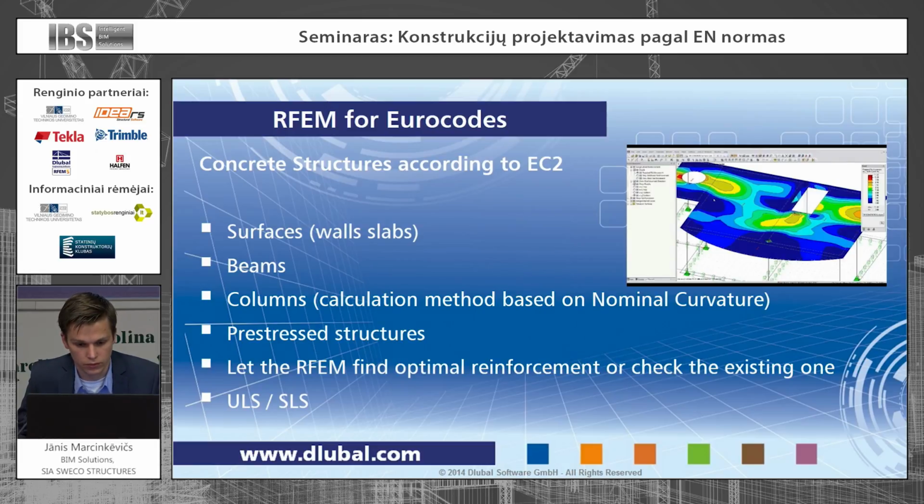in FEM software. Because actually most of the software deals very well with cast-in-place concrete, and there are fixed connections, but when it comes down to precast concrete, where there are, for example, pinned connections between the walls and slabs, hollow core slabs, and in the longitudinal direction, in the case of hollow cores, you need to make a release so that the slab does not make any vertical load on the walls. So for some software, this is problematic. RFEM deals great with that,